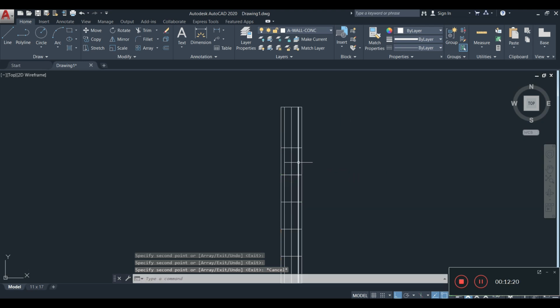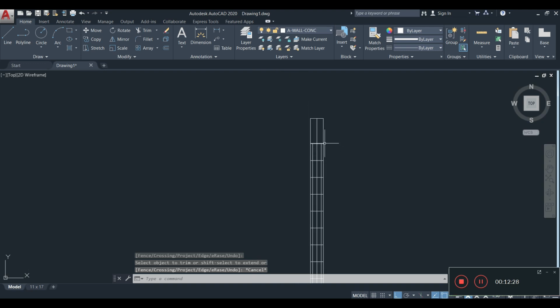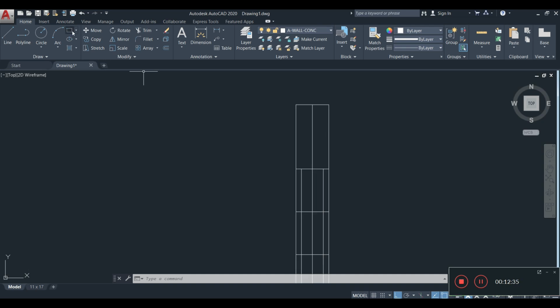Now our belt beam, so let me just stop this right here and trim away here. Now the belt beam is similar to what we did when we were doing the lintel for the sash window, the lintel portion. So it's the same treatment here. Let me just go ahead and draw a little rectangle inside of here. Then I offset that by 25 millimeters. Now this 25 millimeters is representing the stirrup.